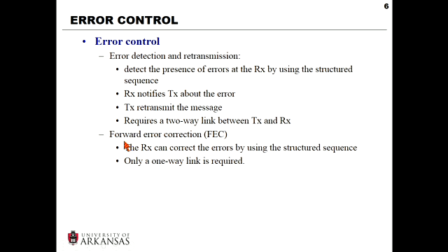At the lower level, for forward error correction, which is the code that we are going to discuss in this chapter, we can use linear block code, we can use convolutional code. We are using turbo code in the 4th generation cell phone systems, and we are going to use LDPC code for the next generation of cell phone systems. These codes are sophisticated enough such that they allow us to not only detect the presence of the error, but also correct those errors if there is any.